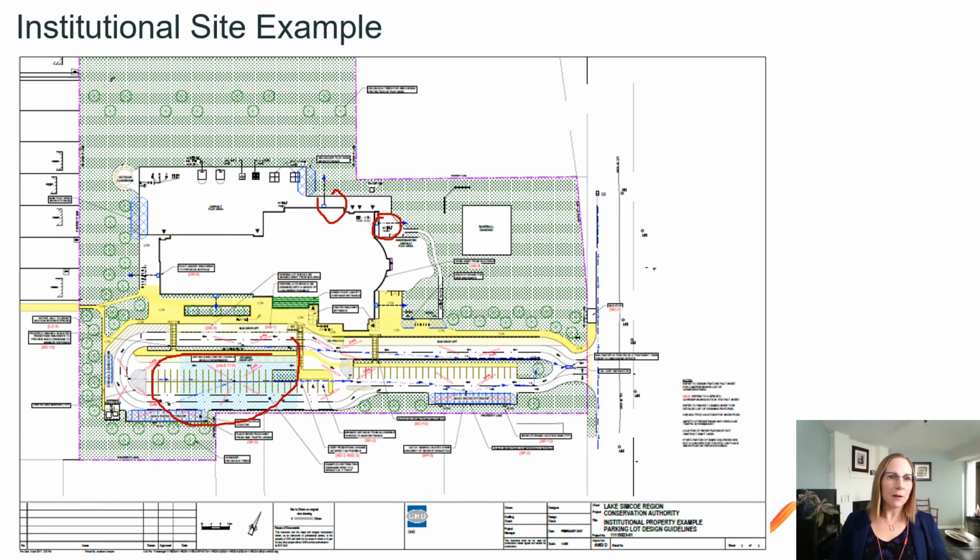And as you can see here, there are also designated snow storage areas for sidewalks and playground areas, which is important in a school. They also specify heated walkways at the entrance, as this is an area that everyone uses, and it will also prevent salt from being tracked into the building and causing damage inside. Regarding landscaping, it specifies native salt-tolerant plants and also urges the consideration of deciduous trees, particularly adjacent to snow storage. In addition, the distance from accessible parking to the main entrance is minimized, and other pedestrian linkages are as direct as possible from bus stops and main parking areas. There's also a green roof canopy over the main entrance to provide some storage and shelter.